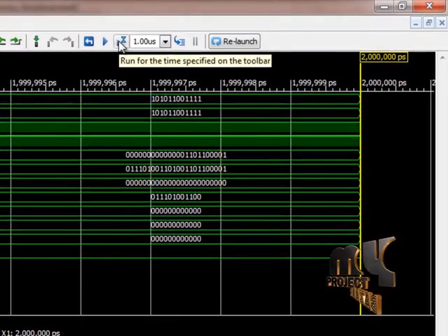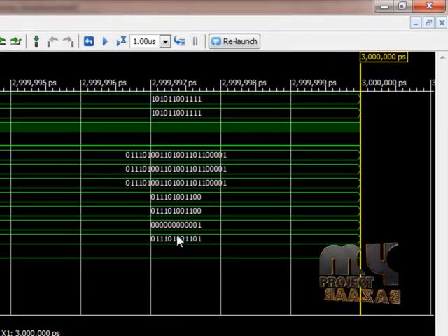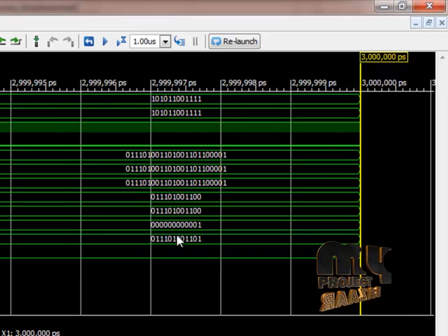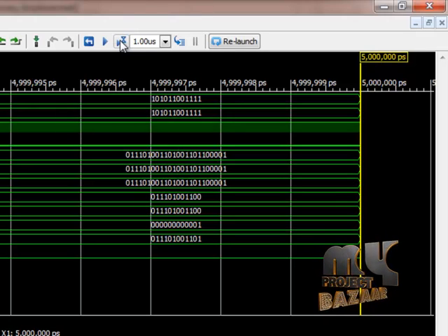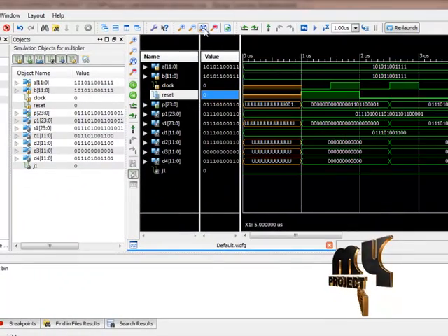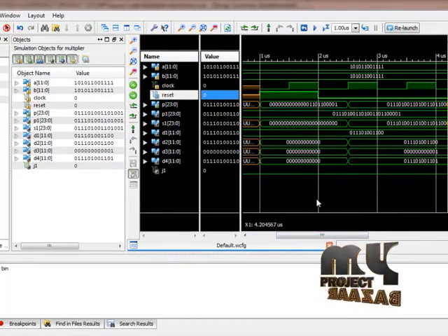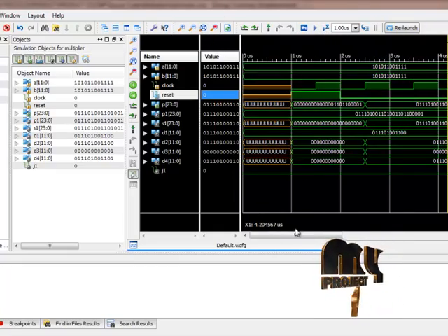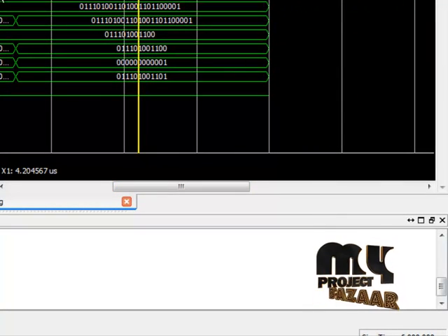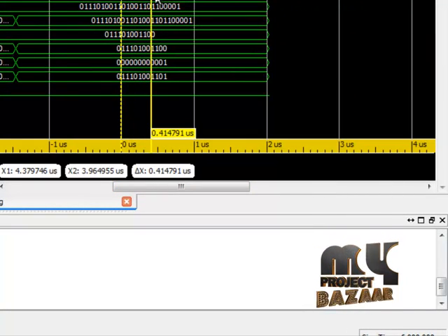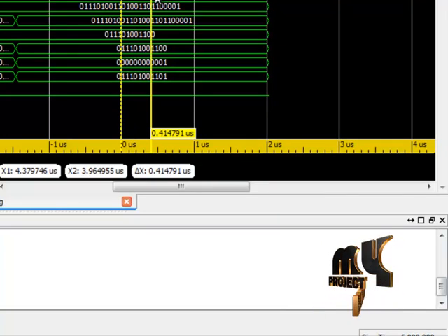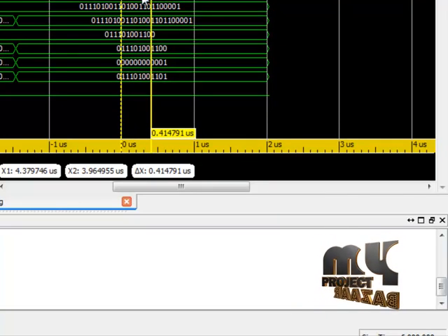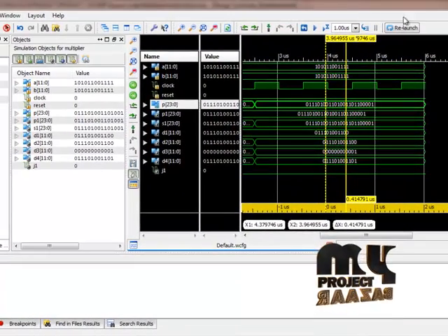So now we run the process. We got the full output for the process. For each and every variable signal we get the output, and we give three types of clock signals as input. We show the zoom function. So this is the multiplier process. We zoom in on the process. We got the result output for the 24-bit from the 12 cross 12 multipliers, giving the output for the 24-bit. So the process simulation is completed.